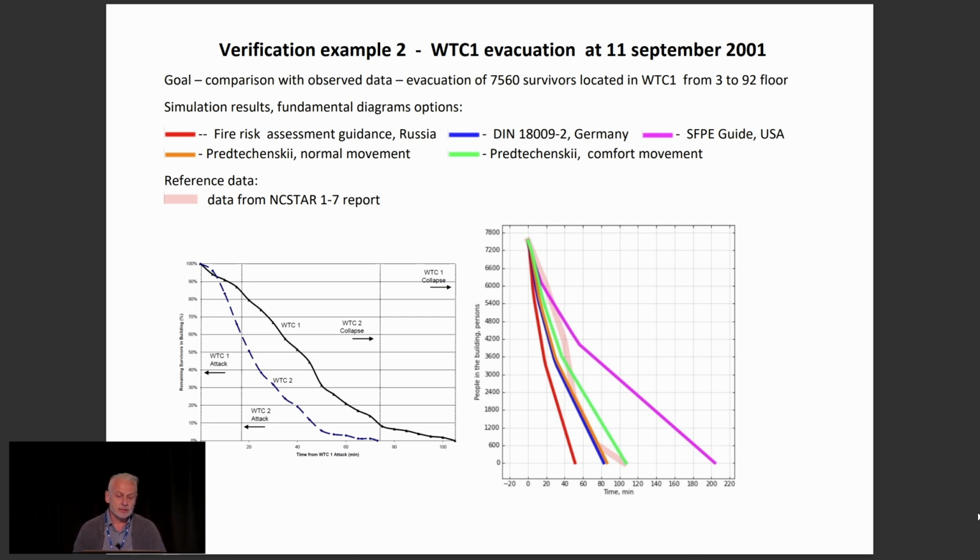On the plot you can see the results of observed evacuation data and results of simulation. The best fit of the results to observed data is the use of the function from German guidance and functions from Predtechensky book. The Russian guidance is quicker than observed data, and SFPE guidance is slower.